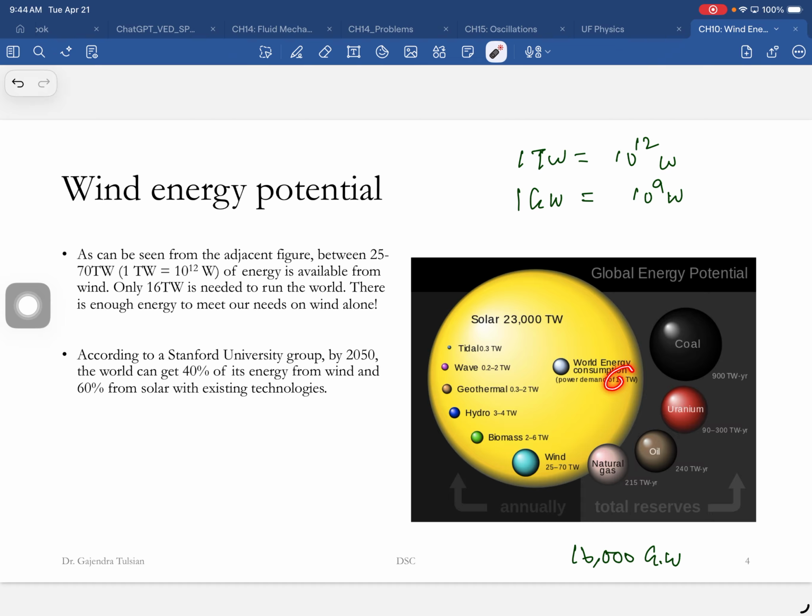For 1 kilowatt hour, the cost on your electricity bill is about 12 cents, and it costs the electric company about 5 cents to produce it. 1 kilowatt is 1,000 watts, so 100 watts times 10 hours. You can keep a 100-watt bulb lit for 10 hours with 12 cents. That's what you can do.